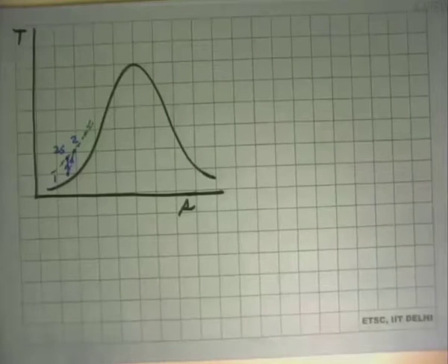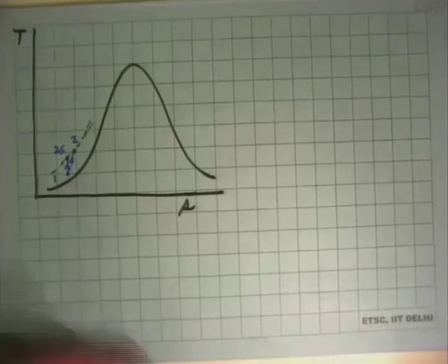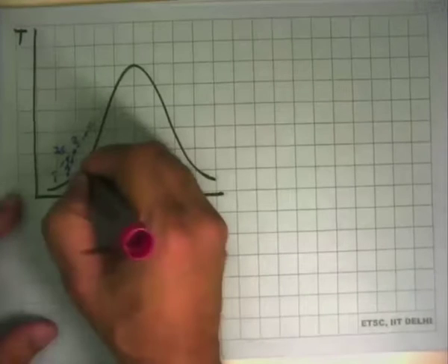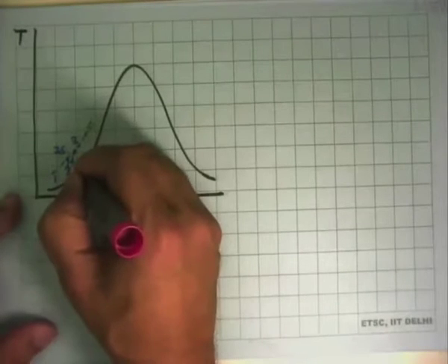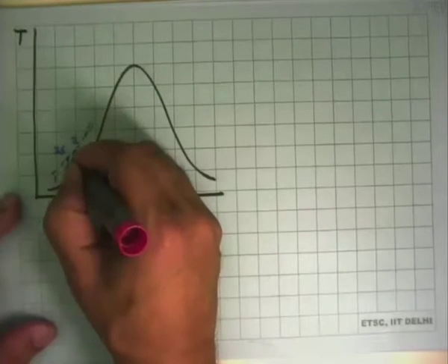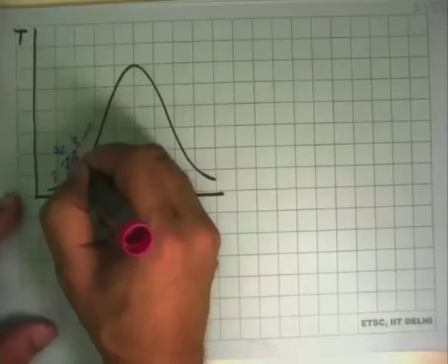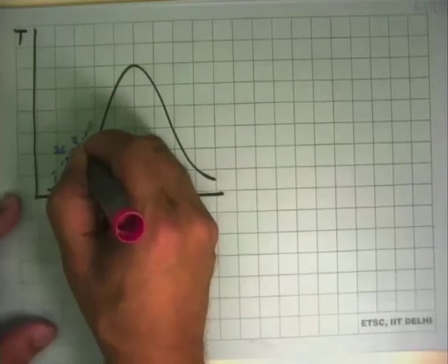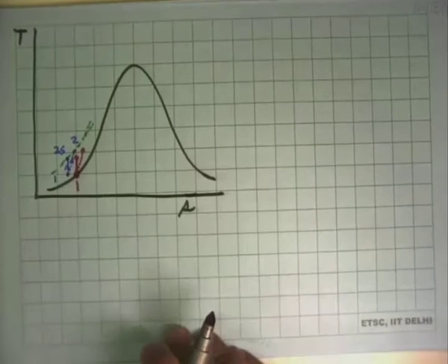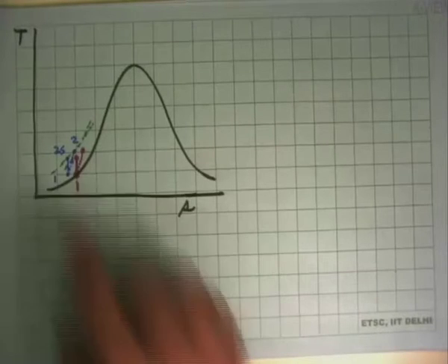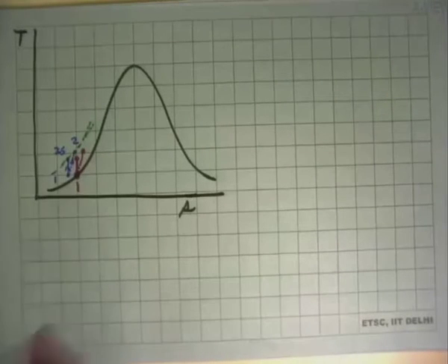If you are saying that we take saturated liquid and then we compress it, that's what happens in a power plant, where we have condensed the water into a saturated liquid and then we start pumping it. So we can say that the initial state was here and then we started pumping it and it went there. So it started as a saturated liquid, went here, and in the ideal case it went slightly over there. Okay, so that's the pumping of a saturated liquid.